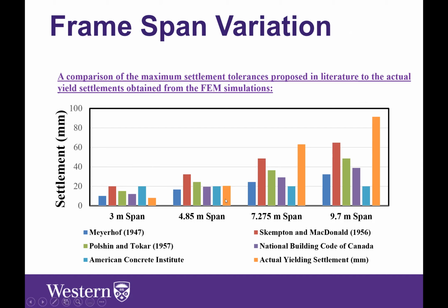Okay. And if we take a look here at the National Building Code of Canada, it actually gives you a better estimate, and it's among the most conservative limits. However, if you look, for example, at the ACI, the American Concrete Institute, at certain areas it's very close. You're basically right within both values, so it's not really conservative over here. So if you're designing, for example, and you're at the limit over here, you're playing for your luck, basically.